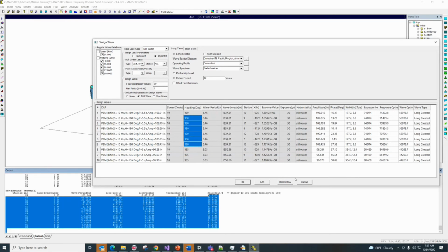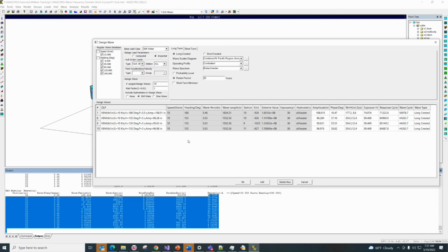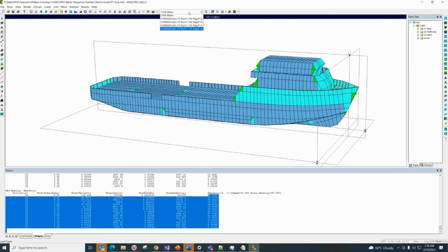So you probably say, oh, I don't really need those, I delete those and I just pick this. So likely these two load cases are probably the concern for the design. So now we have these two load cases. We say, okay. And now you see in the static analysis, we automatically add 4 load cases. This is sagging, hogging, because it's a linear case. And this is another phase angle change from 0 plus 180.